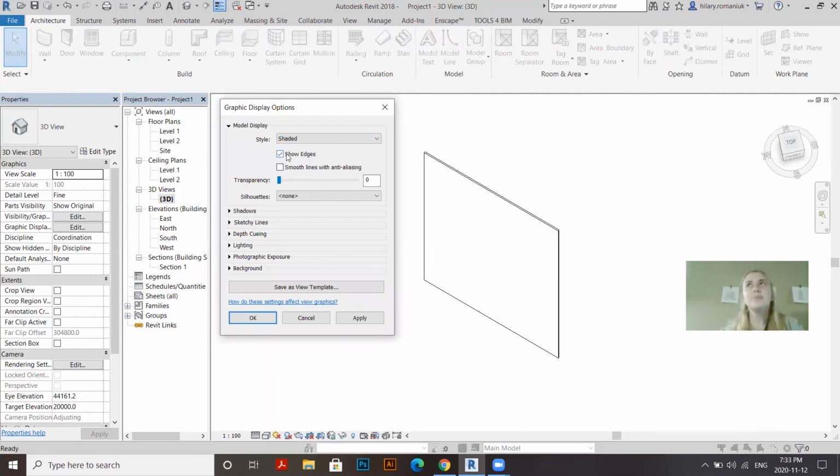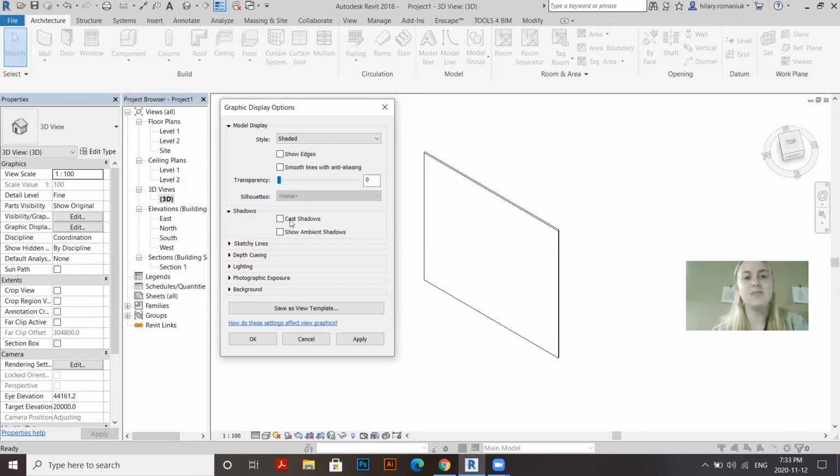And if you're using this BIM as a studio project and you're not exactly modeling everything perfectly and it's not all clean because you're just trying to get something to show your prof and nobody's ever going to open this BIM anyways, I like to turn off show edges, because that's where your model tends to look not very clean, when those edges overlap and things aren't joined. So turn off those show edges and then have some fun with these shadows.